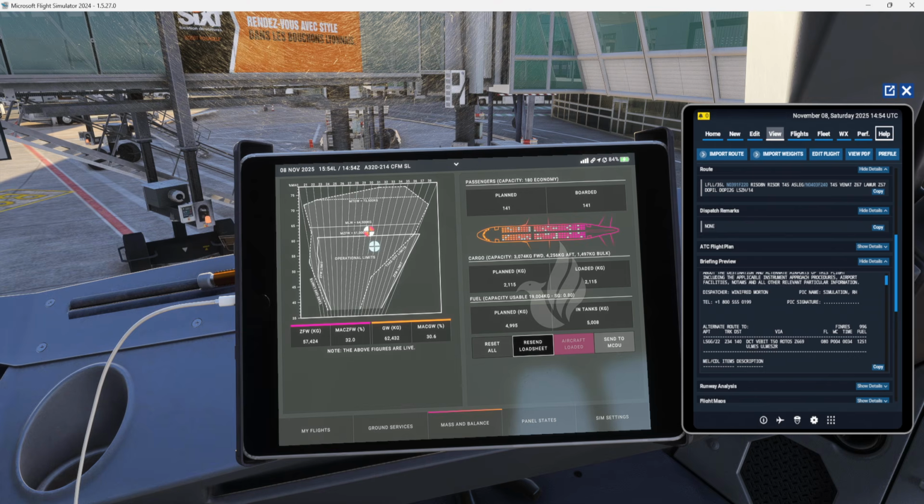The traffic load is the total weight of all payload that we have on board, packs, cargo, and baggage, excluding the crew, because the crew and their baggage are not included in the traffic load. So the crew, baggage, and mass are included inside the dry operating mass, and the dry operating mass plus crew and standard equipment equals the basic empty mass. This we have clear, no?